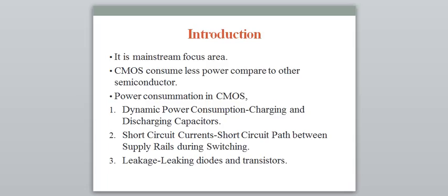So what is the introduction? In the introduction, the power in CMOS is a mainstream focus area. The whole circuit working depends on the power consumption. CMOS logic dissipates less power than NMOS logic circuits because CMOS dissipates power only when switching. CMOS gates are very power efficient because they dissipate nearly zero power when idle.